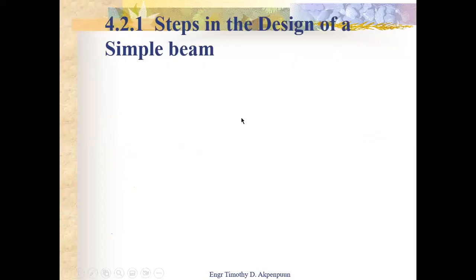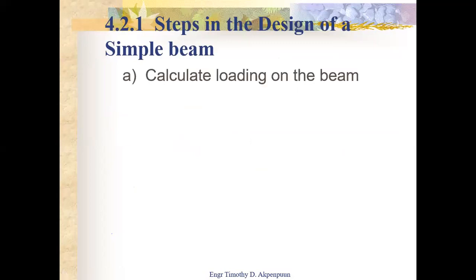Yes. So steps in the design of a simple beam. 1, calculate loading on the beam. If you have point load, you are all right. What do you need to do? You just need to calculate your reactions from the 2 supports. But if you have a uniformly distributed load over a platform, you must resolve the uniform distributed load to a point load.